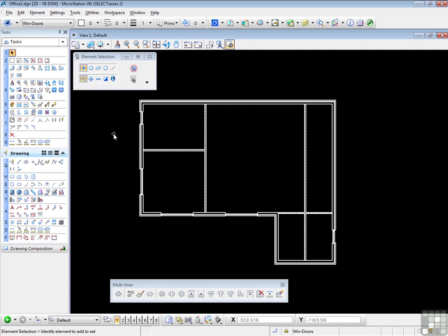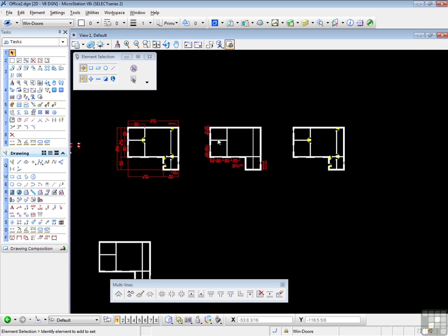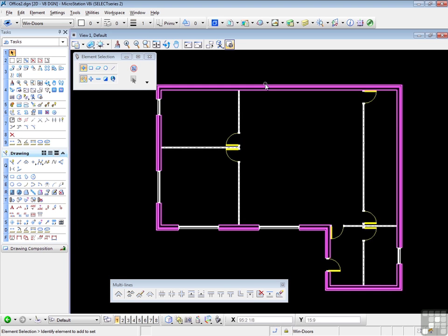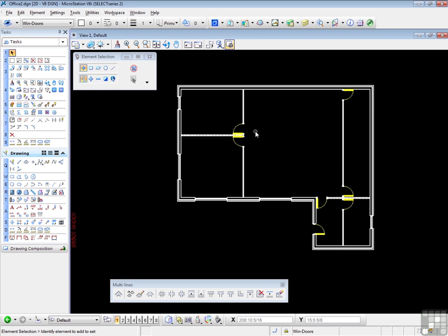Next thing is to insert some doors. And I haven't given you any door dimensions, but again, if you look at your file, you'll see that we obviously have doors to each of the offices. And this one has 2 doors. Now, I couldn't make a door symbol, of course, but it's easier to use a pre-existing cell.